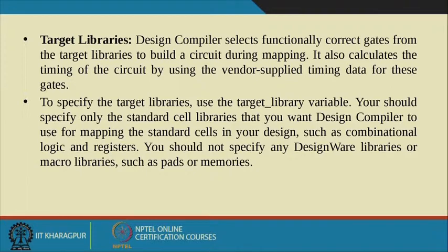So what is your target library? It means the technology in which I am going to implement my circuit. There are several foundries like TSMC, UMC, and Austria Microsystems. The foundry in which I am going to fabricate my chip is basically known as the target library.